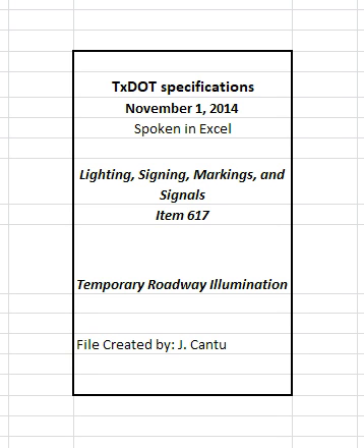The engineer may shift the locations, within design guidelines, where necessary to secure a more desirable location or to avoid conflict with utilities. Use utility-grade materials for overhead electrical work. Maintain a minimum of 22 feet clearance above the roadway for overhead electrical work. Do not support overhead wiring with existing luminaire poles or breakaway luminaire poles.